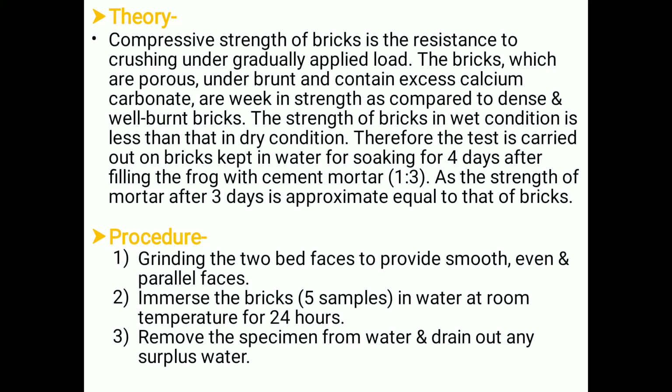Then we have to grind the two bed faces to provide smooth, even and parallel faces. After that, immerse the bricks in water at room temperature for 24 hours.